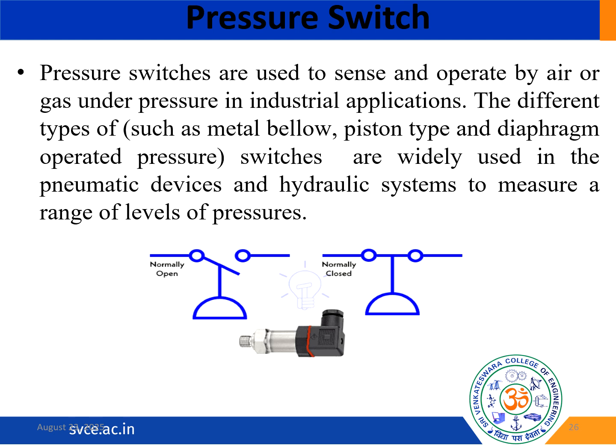So pressure switches are electromechanical devices, which are commonly used in electrical or industrial automation and in control systems. When the pressure reaches a predefined value, the switch activates. It can either open or close the electrical circuit, and it can also initiate control actions such as starting or stopping equipment.